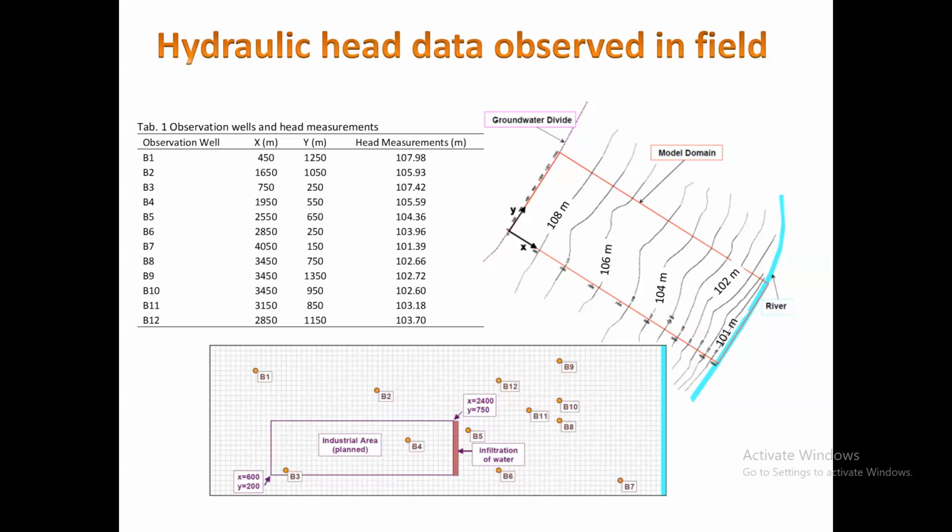Okay, so let's start. Let's open ModelMuse and use it first of all to generate our grid, the grid where we'll be solving for the head value. Then after we generate our grid, we will enter our conceptualization for the hydraulic conductivity field, as a change in X and a change in Y. And then we will enter our boundary conditions, like the recharge that we have from the top, the pumping well, and the drain.